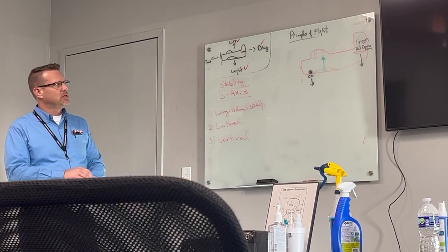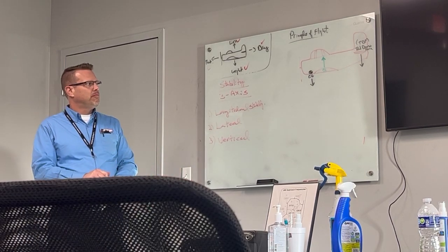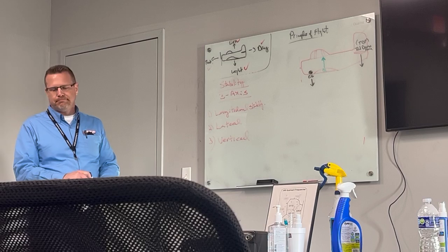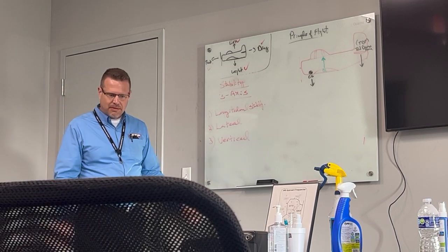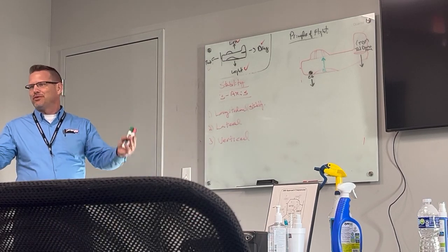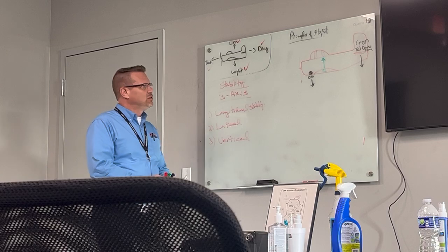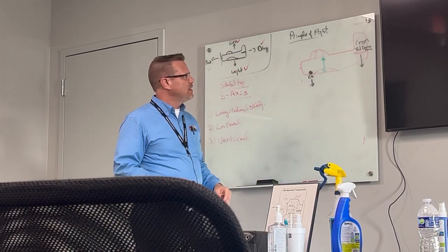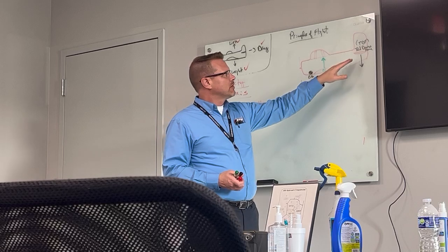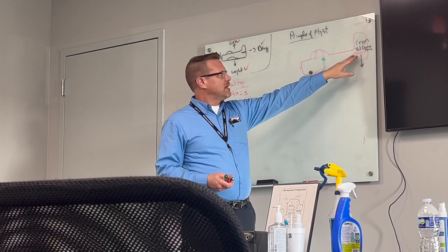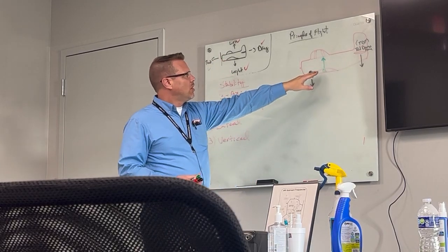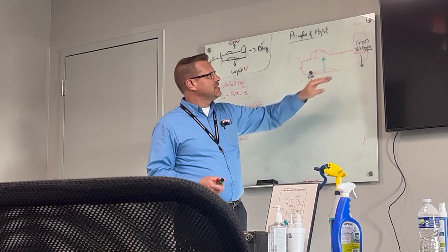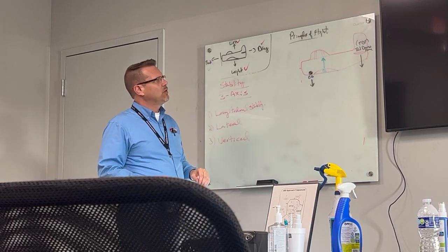Tail down force is created by our horizontal stabilizer, or whichever one you have, right? We have different ones. The way it's created is basically our elevators and horizontal stabilizer there create lift in a downward motion. So it's an upside down wing.